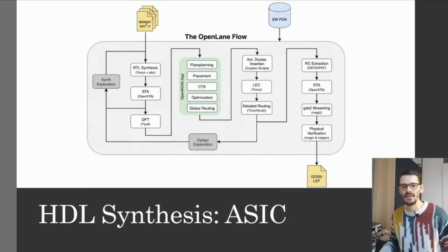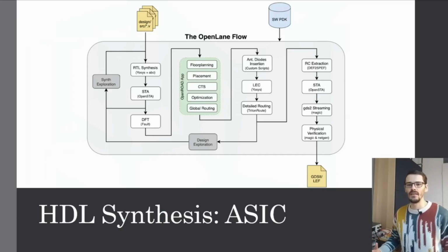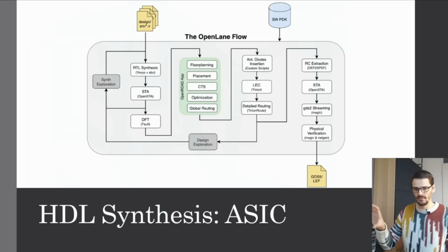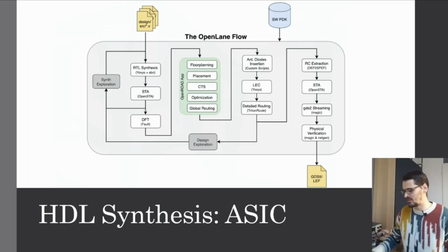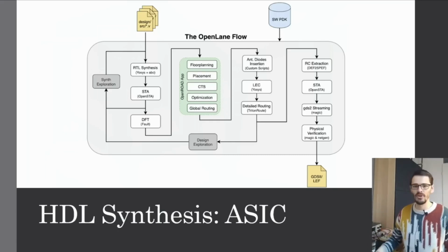The important thing is that in an ASIC you synthesize to a standard cell library, which is just transistor blocks that you can actually put on an IC. Whereas with the FPGA you synthesize to the lookup tables, multiplexers and flip-flops inside the FPGA in a fixed way.